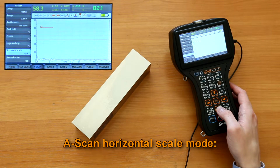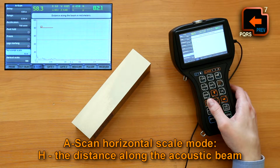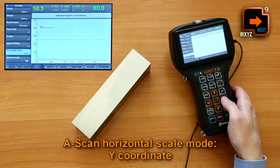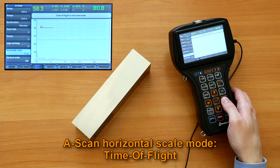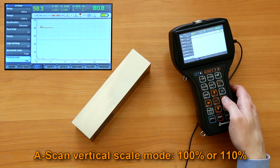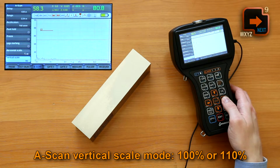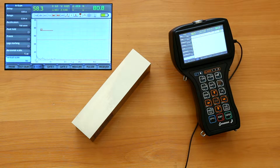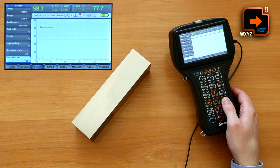A-scan horizontal scale mode: the distance along the acoustic beam, y-coordinate and time of flight. A-scan vertical scale mode, 100% or 110%. Here I'd like to mention that both Sonocon family instruments can take correct measurements for off-scale signals whose amplitude does not exceed 220% vertical scale.